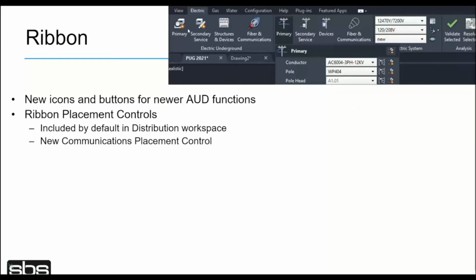So just imagine all these panels listing out, all of your facilities and picks organized the way that you want, and then that's all loaded just with your template. So you don't have to worry about potentially rolling out a CUI file and things like that if you can follow the rest of the out-of-the-box layout on the ribbon. So we have some folks using that, and it does make the deployment management much simpler by not having to manage a separate set of CUI changes. It better consolidates all this information in your template, and provides you with the ability to lay everything out.